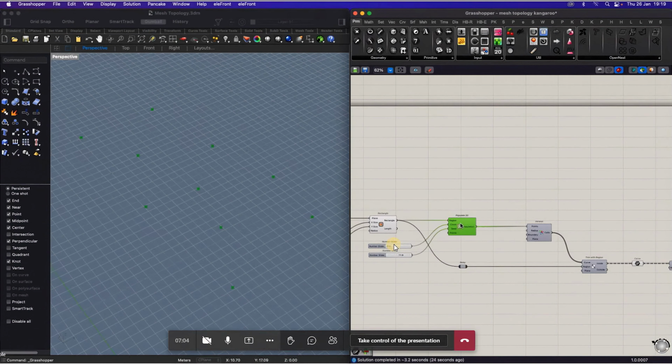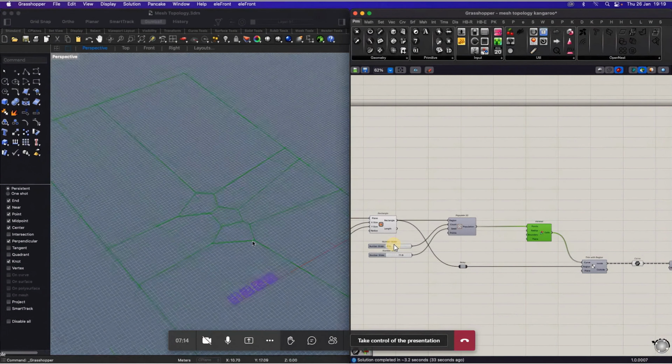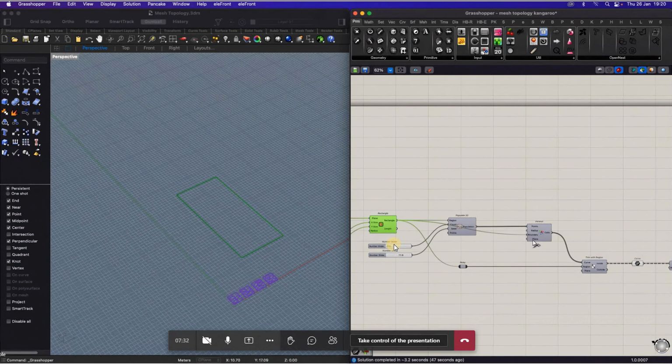And then once you've defined the points, there's the Voronoi component, which is typically a bit overdone in the industry. But it uses those points to create the Voronoi pattern. Usually in other tutorials I've seen, they just use the same rectangle that they use to populate with points, and create a boundary around that geometry. If you do that, you'll see that the Voronoi shape actually gets trimmed. So if I click on it now, it's just going to be a neat, clean one.